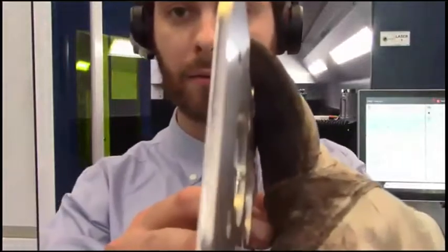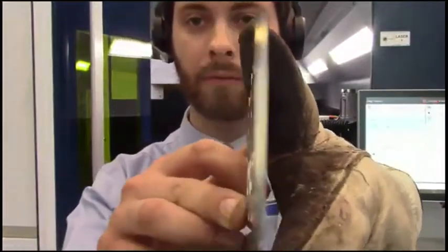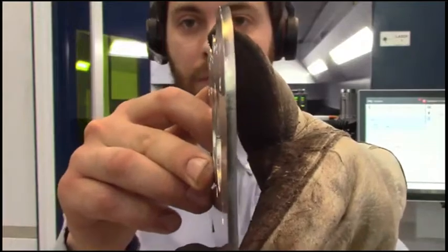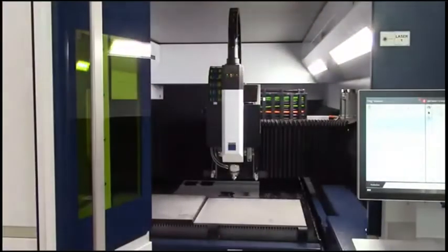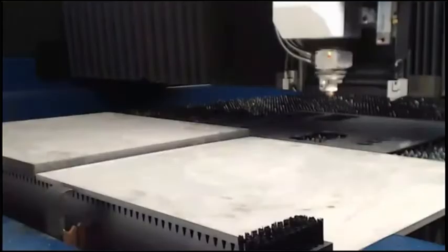Yeah, absolutely. And the great thing about that machine, and we don't want to have all the fun stuff dealt with today, we want to have a reason for y'all to come back. This machine has what we call active speed control on it. So in the near future, we're going to do another webinar where we highlight that feature, which is autonomous. It's the closest you can get to being totally automated with a machine. It's a technology that actively looks at the kerf and says, okay, the material quality is not so good. We've got a little bit of rust on the surface. The material is inconsistent. It's just some random A36 somebody dropped off on my loading dock that I need to cut, and the laser will automatically adapt.